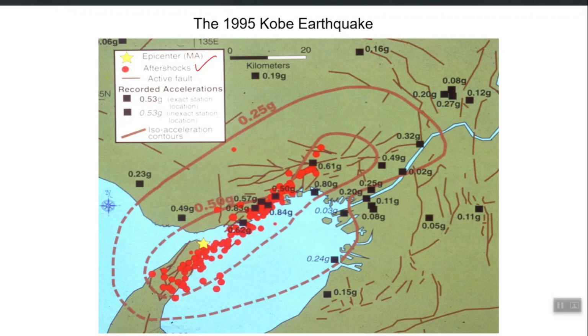The shaking which is experienced by our structures is the one experienced on the surface, and not at the bedrock level, right? Sometimes the station is resting on loose soil, sometimes hard rock, sometimes directly on the surface, sometimes 10 meters below the surface. Loose soil can amplify ground shaking, and stiff soil can de-amplify it also, right? So the local soil effect can modify that general trend.